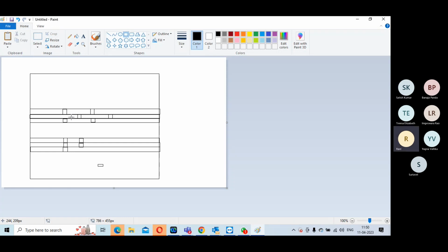That rule comes from your technology file. The technology, or your foundry document, will give you the data telling you what the tap requirement is. That comes from the vendors: within 50 micron, I need a tap.